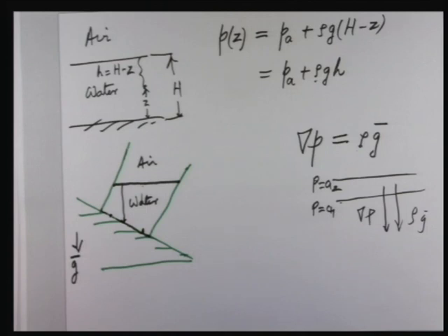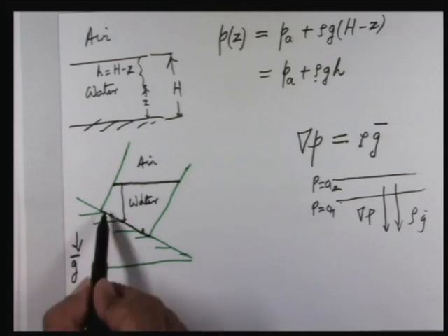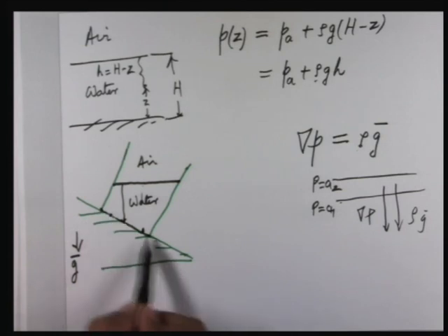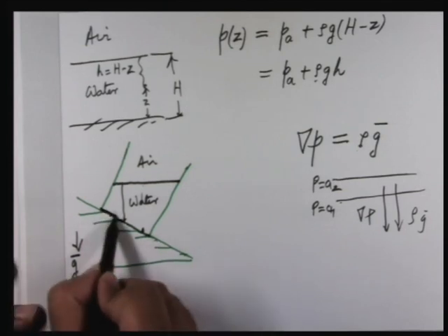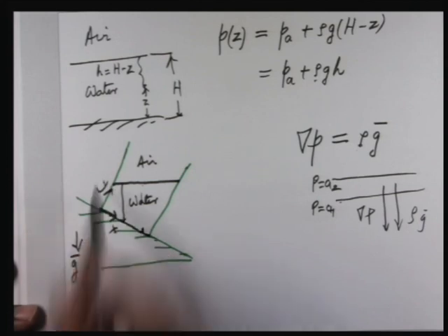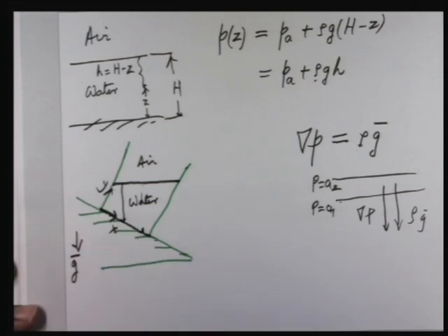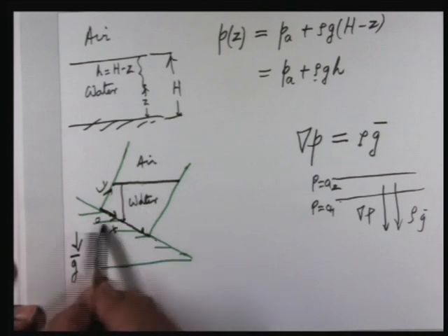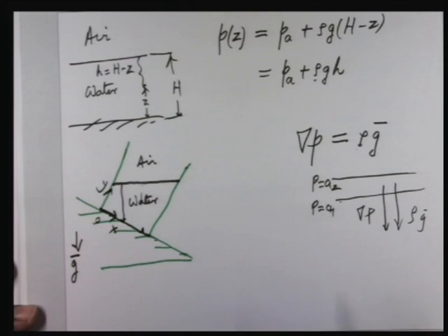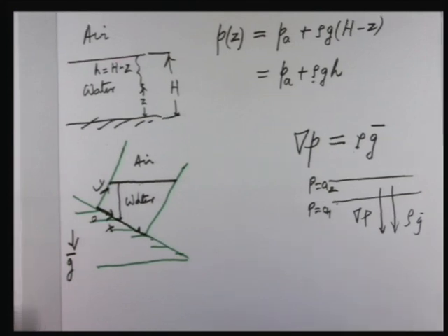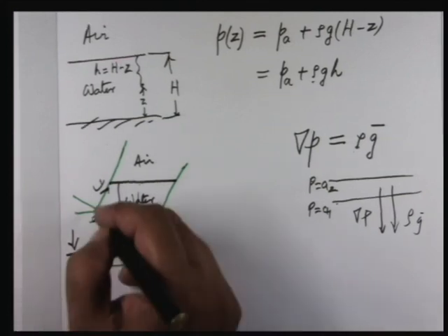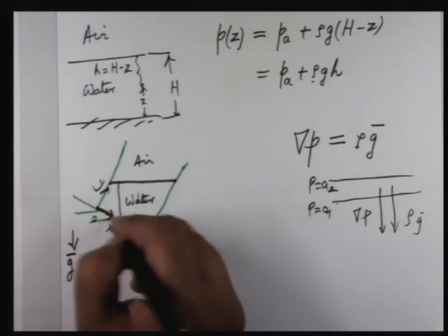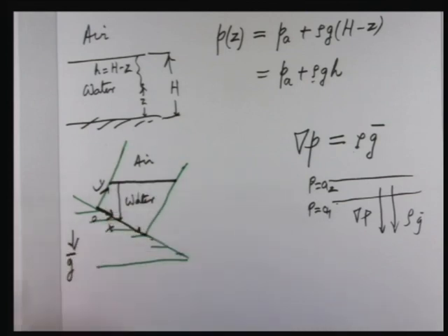Okay. So you need to know how the pressure at the bottom is varying with some coordinate, and it's convenient if I take x to be this and y to be this, maybe. Okay. If the origin is here, then the net force will be the integral of P at y equal to 0 dA. Okay. So here you cannot take the z axis. If you choose this coordinate system, the z axis is not in this direction.